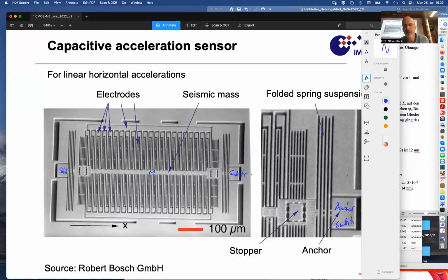So all this element down here, including this thing up to here, you could think of as a spring, and then there are more mass pieces attached to it sideways. Those sideways elements are electrodes that need to be attached to sense its motion. So we have the central so-called seismic mass.